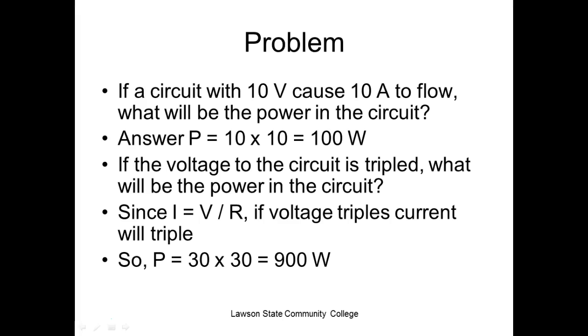We do a thing in motor controls. We take a light bulb. We do it on purpose. We're simulating bad connections. So we're putting resistance in a circuit that's not supposed to have any in there. And we use light bulbs. And the way it calculates out, the light bulbs only have 30 volts across them. And people think the circuit's not working because the light bulbs don't light. But they're rated at 120 volts and we're only giving them 30 volts. Right? They're doing what work they're supposed to do, but they're not doing enough work to light up.